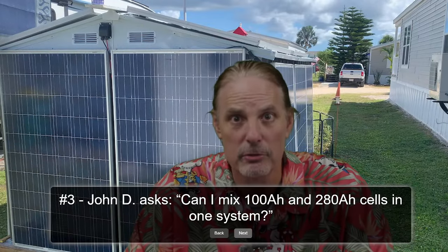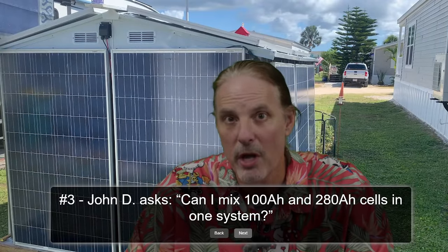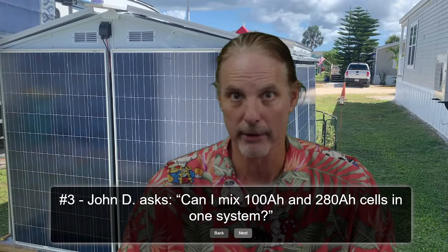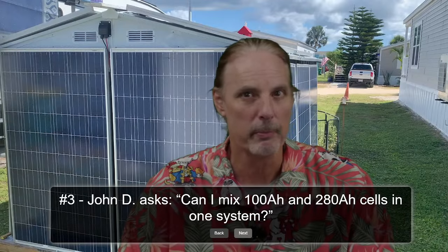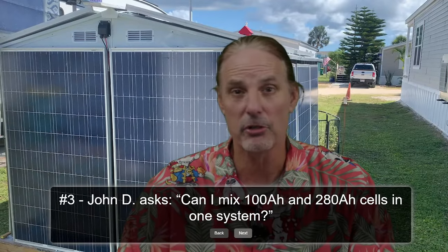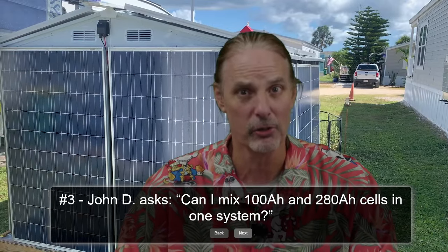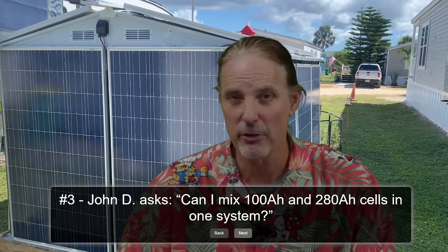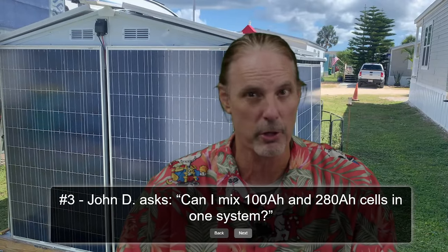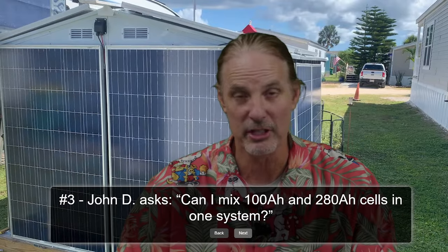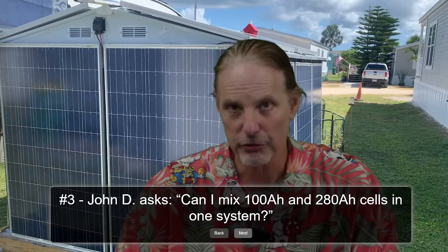I have a system with 3 100 amp hour batteries and 1 304 amp hour battery. I do not use closed loop where they're reporting to the inverter. I let it base on power. There are some ups and downs, and a video I released earlier today covers a lot of those in great detail. I'm going to quickly go over them so that I answer the question, but I'm trying not to go into too much detail, seeing how I've got something out on it already. But the fact is, yes, you can do it.